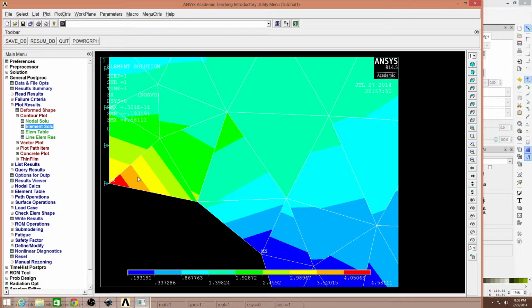This will provide us more accurate results by having more nodes and more elements. It also increases the compute time. This can be a bad thing if you are doing something as simple as this, but is good if your results will actually be used in the professional world.